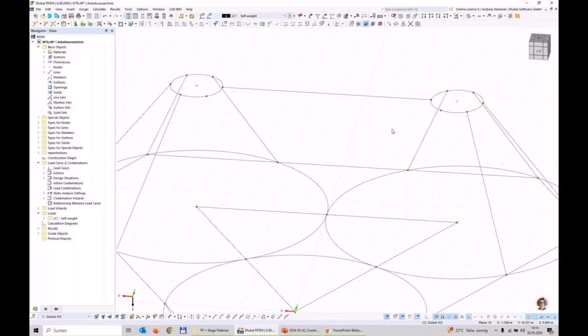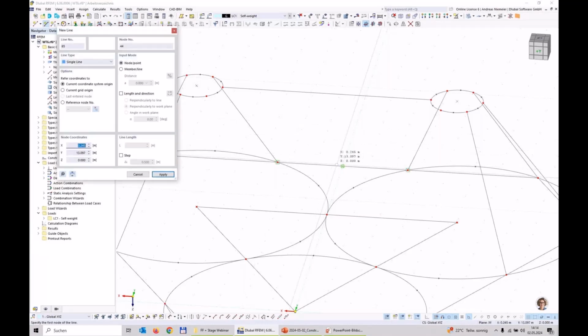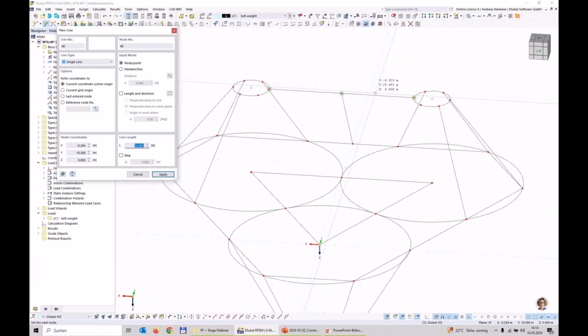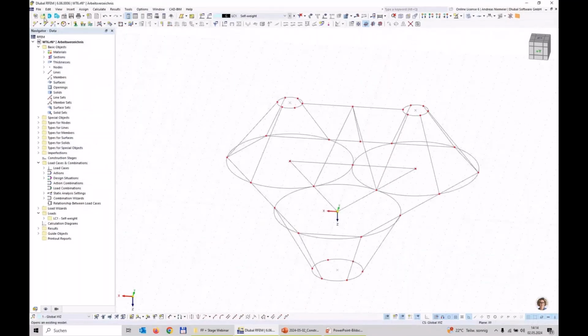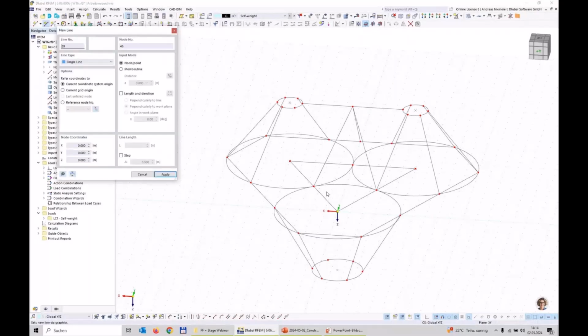So I cannot model it, and I don't want to waste time with it. I only want to model the structure as roughly as possible in space, which allows me to mesh it with flat mini surfaces. Here, let's say I don't touch the node, and later I say to the computer, the RFEM, please find me the optimal shape.